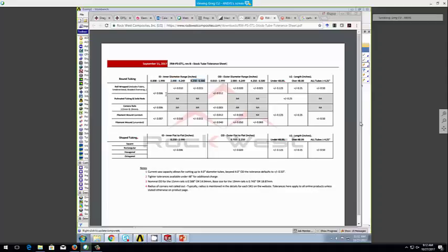So just said the axis, the load factor versus an equivalent airspeed. For us, we'll be flying low enough so that our flight density is equal to sea level density. So the equivalent airspeed will be equal to our actual airspeed. We have the limit load factor, which we designed to, but we've got to add some safety factor to that. Typical number is 1.5 times the limit load factor. So we'll design this ultimate load factor so we have some safety factor, which is usually 50%.